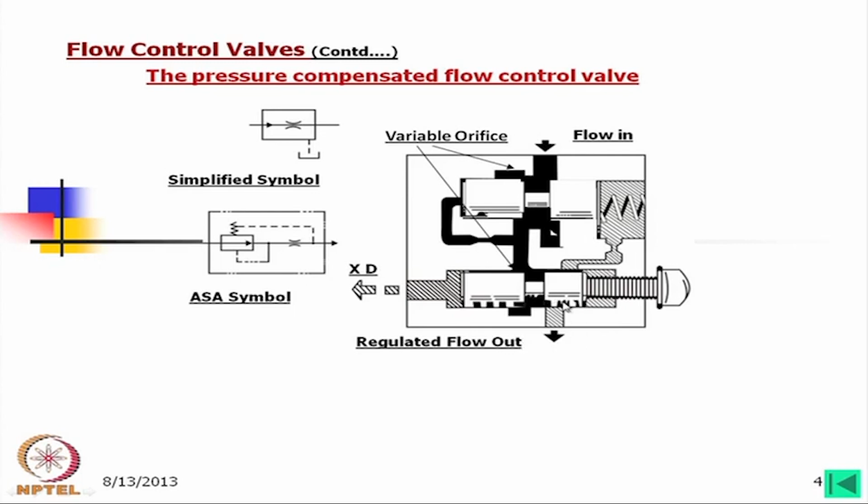Now, it is difficult to understand just by these words, but you need to study these valves thoroughly to understand what is happening. Always keep in mind that wherever there is an orifice, the flow will change and there will be a change in pressure drop once the flow begins through these valves, and ultimately this pressure difference keeps this spool in balanced position for a longer time.